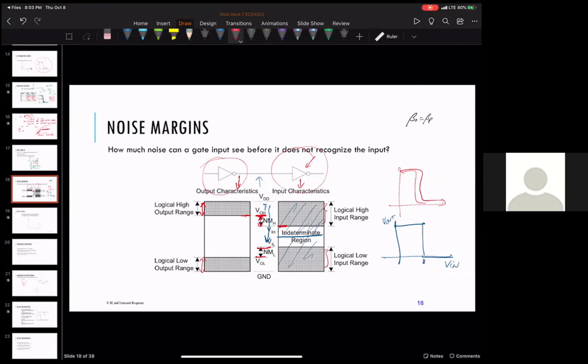So as a designer, you have control over the noise margin. You end up designing it for the typical case, or the nominal case, and then you have to simulate it. The other thing is we saw how temperature also changed current versus voltage, and power supply changed current versus voltage. All those things are changing your betas.